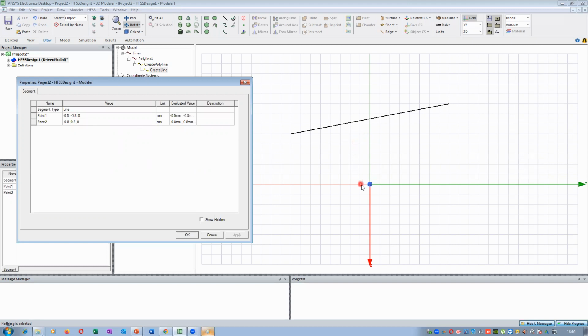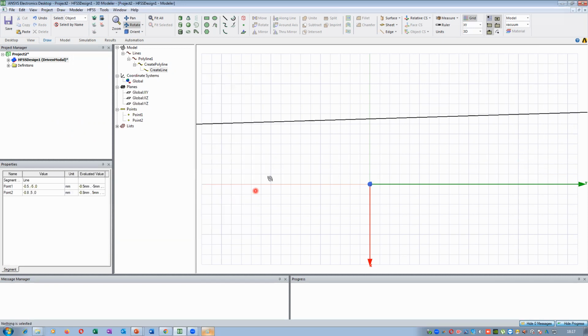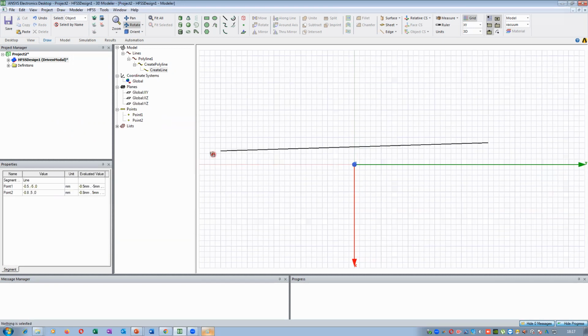As the x-axis is dividing the line into equal parts, the 10 mm becomes 5 mm. That means minus 5 as the y coordinate of the upper point, point 1, and plus 5 as the y coordinate of the bottom point, point 2. Now click on apply, then click OK. Now check how the structure became.